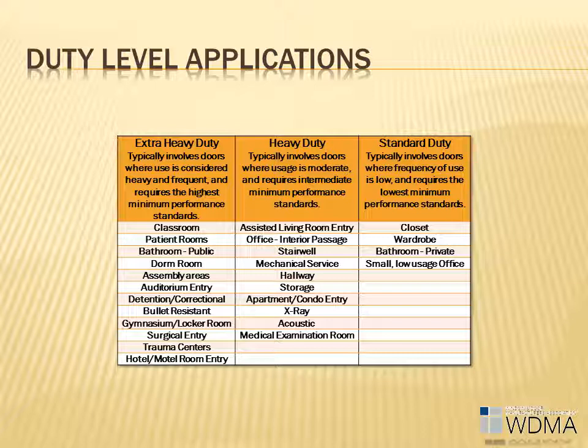Older, pre-2004 editions of WDMA's architectural wood flush door standards used aesthetic grades, premium or custom, not only to describe the appearance of the door, but also to imply a level of functionality. Premium was felt to provide greater overall strength than custom.